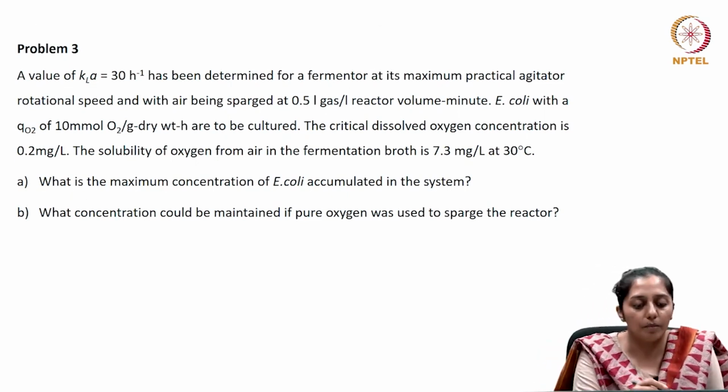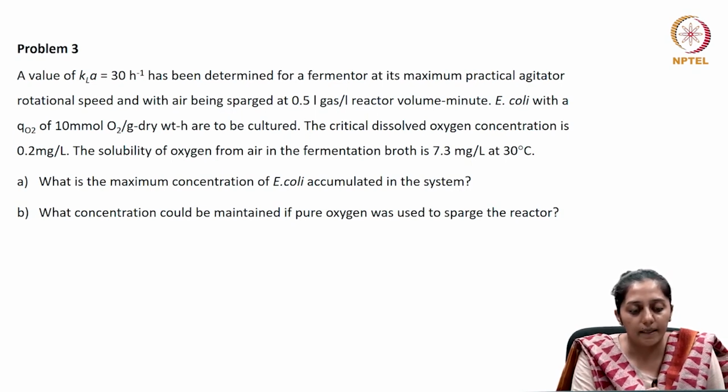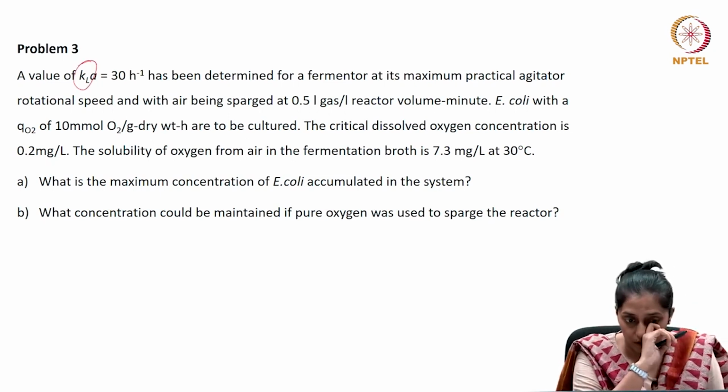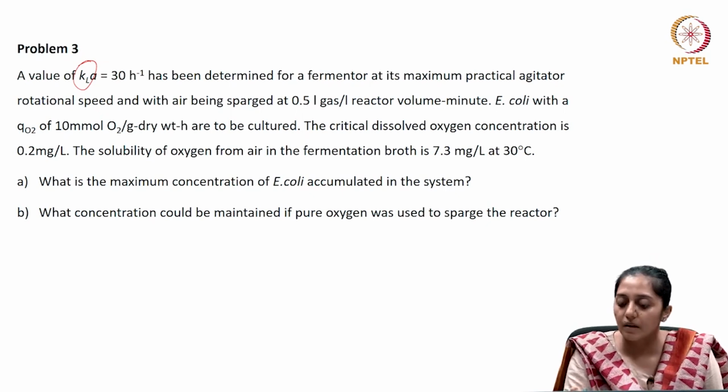Let us see the third problem now. A value of KLa is given as 30 hour inverse. So, the volumetric mass transfer coefficient of the system is known for a fermenter at its maximum practical agitator rotational speed with air being sparged at 0.5 VVM.